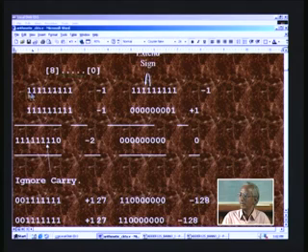So by looking at the MSB, you can distinguish whether this is in 2's complement. So you can recognize this as a negative number, that is why you put a negative number here, and if you evaluate the 2's complement of this value, out comes the magnitude. Let us look at the 2's complement. We have to retain the first one here and replace all of this by 0. That means it boils down to nothing other than 1.